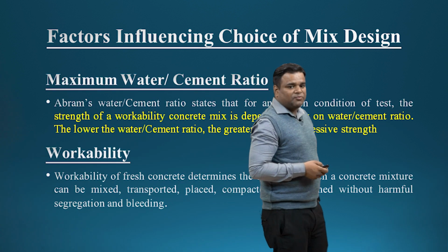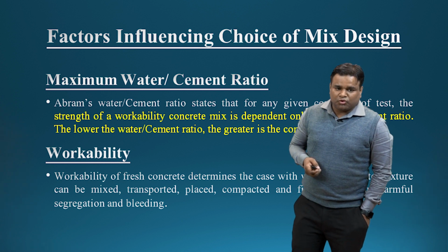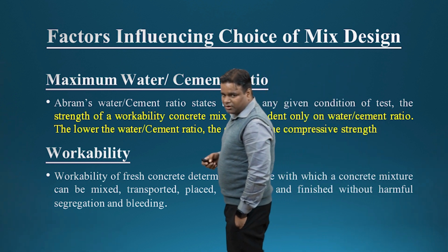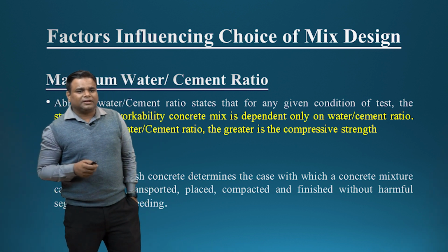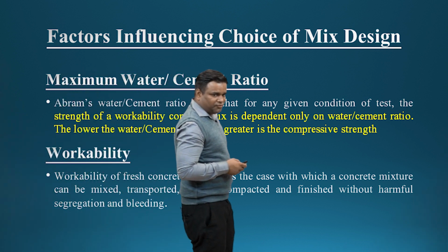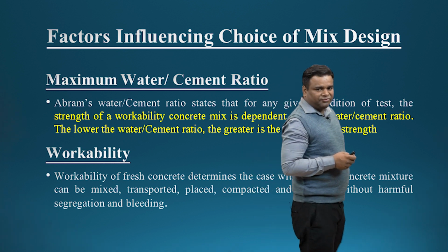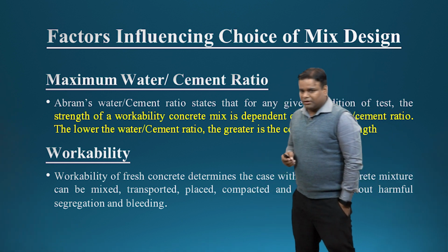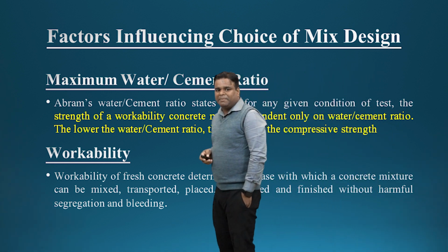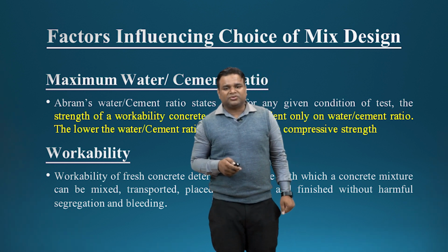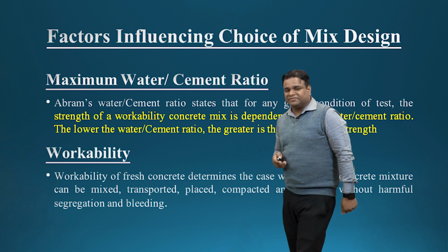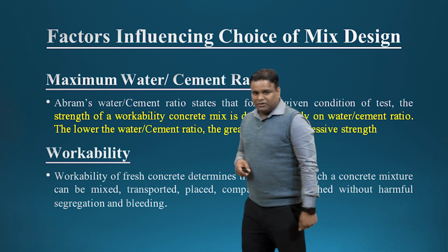Then the maximum water cement ratio. As per Abraham's water cement ratio law, for any given condition of test, the strength of a workable concrete mix is dependent only on the water cement ratio. The lower the water cement ratio, the greater is the compressive strength.